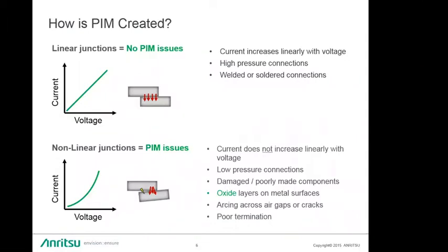So a little bit of PIM concepts here. PIM is created when you have some sort of a non-linear device. This can be a diode. This can be a transistor. This can be rust. Now, if you think back, a diode junction is some silicon with some impurities in it. Now, if you get other things with impurities in it, they also have this logarithmic response between current and voltage. Rust, it's called the rusty bolt effect quite often. And when you have this nonlinear effect, PIM